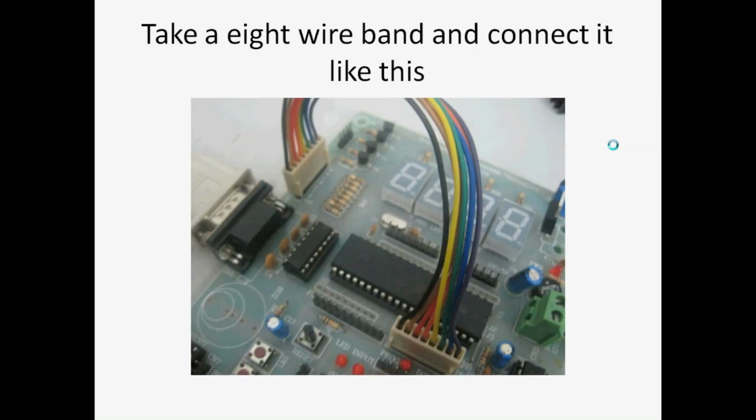LED 7 segment with 8051 practical. First of all, we need to connect the 7 segment data pins to any of our ports. So I have used an 8 wire band to connect the 7 segment to port 0.